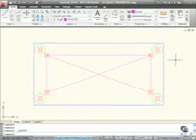Now, there are two ways of doing this. You can edit your object properties by way of your Layer Properties Manager here, and change color, line type, and line weight here in the Layer Properties Manager. What that would then do is it allows you to work with the by layer setting. So basically, by layer, what you're doing is saying that when you draw an object on the center layer, it's going to be cyan, it's going to use the center X2 line type, and it's going to use the default line weight. However, you can change that individually.